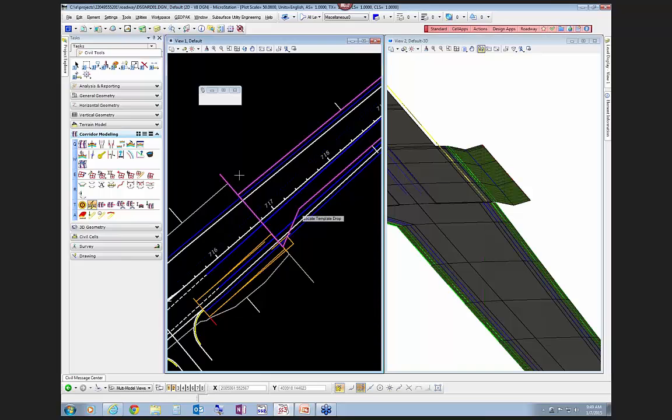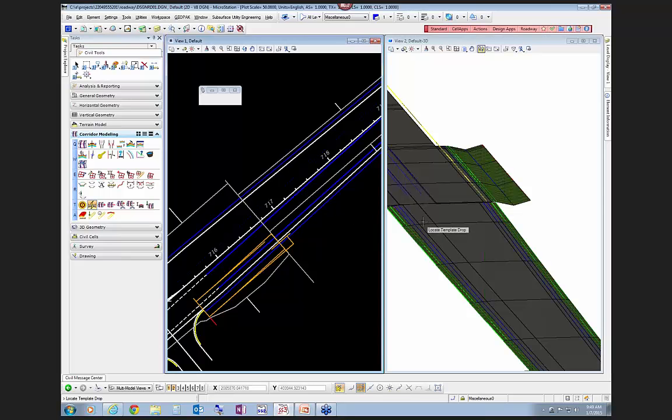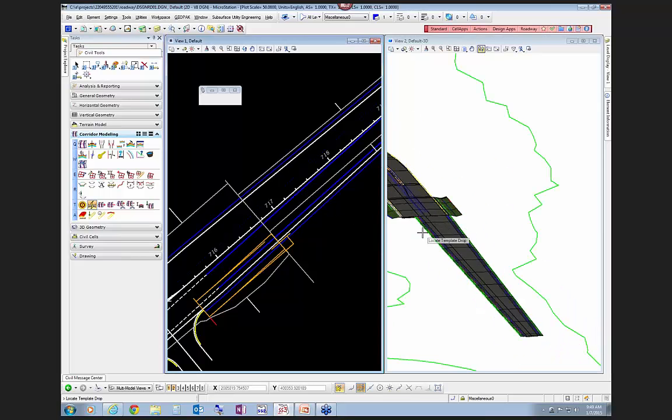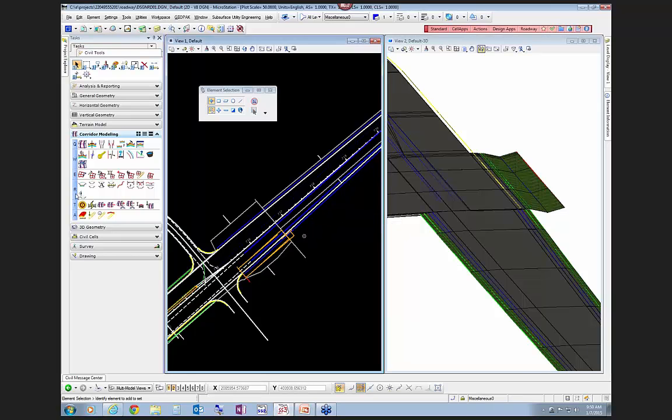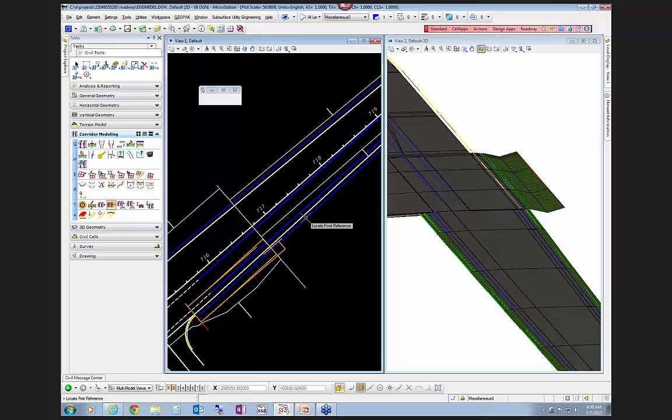The other thing you can do to troubleshoot these things, and this is all part of testing these ranges, is to drop the reference and add it back in there. It's not as easy in SS3 to see these as it was in the Roadway Designer, and see, just by doing that it sort of fixed that. So now, actually no, it didn't. So what I would probably want to do is come in here. It says it's referenced by that corridor, but it's obviously not working. So I'm going to subtract it from this corridor and then pick this line and reset it.